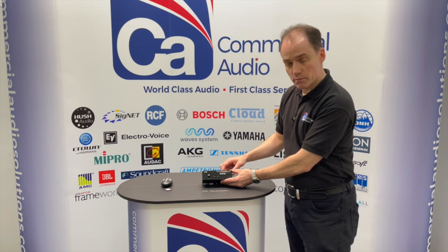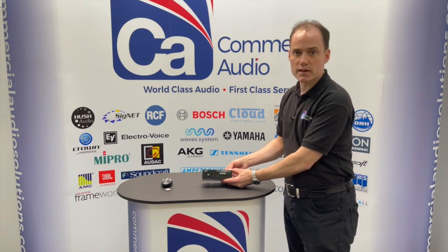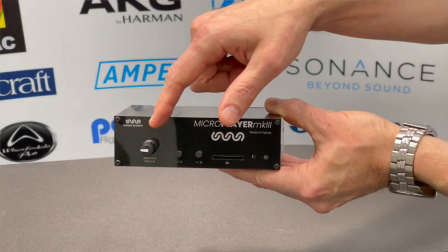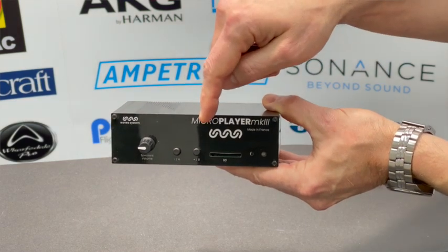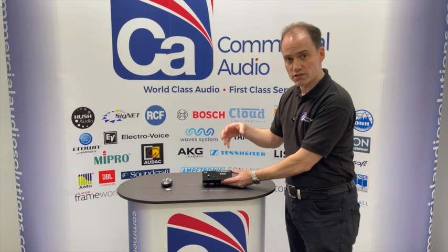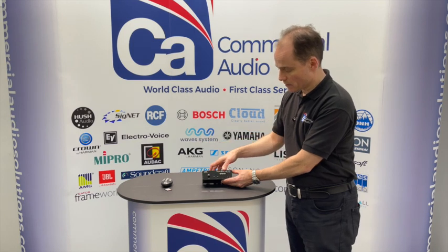There's a built-in amplifier which gives you 2 by 10 watts, so you can power 2 8-ohm speakers if you want a little standalone system. The volume control on the front just alters the volume level to the speakers. These 2 buttons can be programmed to start messages, stop messages and various other functions. That's done in the text file on the SD card when you program it.